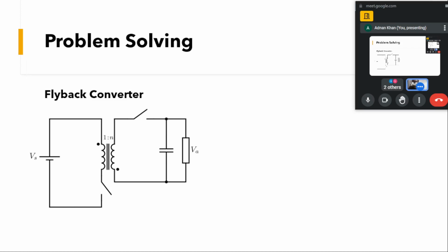So yeah, this is the topology for the flyback converter. This is isolated. Here we have introduced some isolation. If you are able to see this portion, this is a buck-boost topology. If you remember, we had an inductor at the input, and then some switch, then a diode, which was able to do the buck-boost type operation. Here, this is an isolated buck-boost topology.